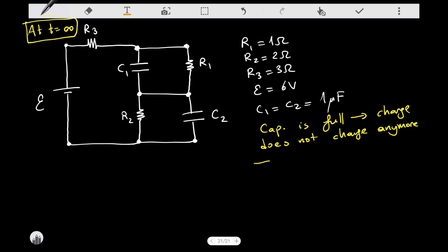Whatever the charge variable is, this means that the rate of change of that charge variable is equal to 0. But we have mathematically connected the derivative of the charge on a plate with a current that's flowing through that plate. So therefore, the current on the branch where the capacitors are is equal to 0. So that's essentially the physical idea.